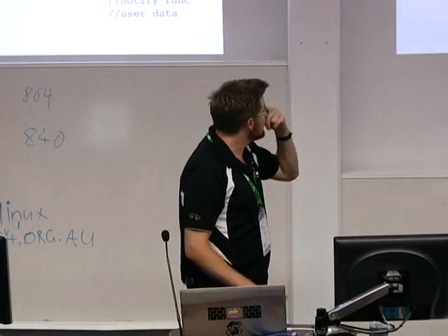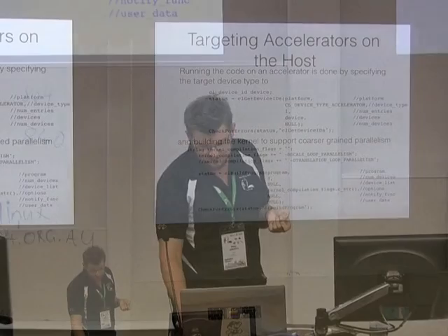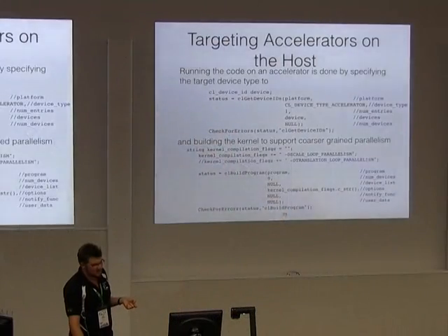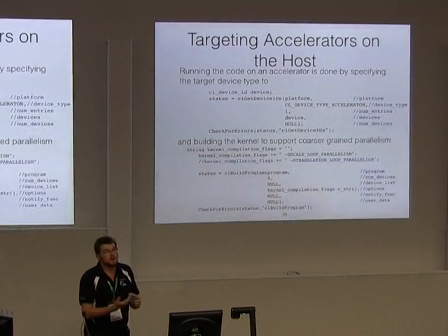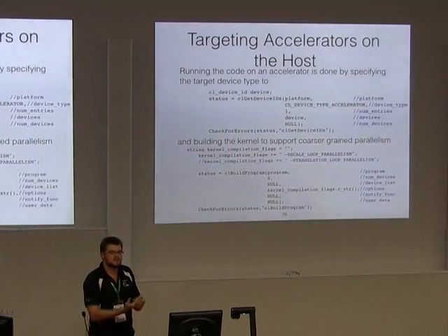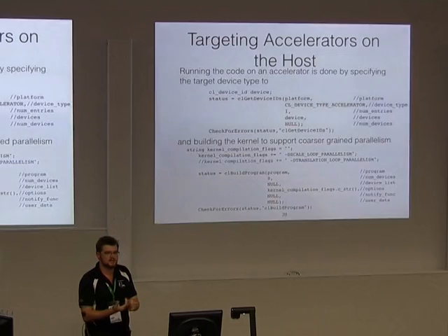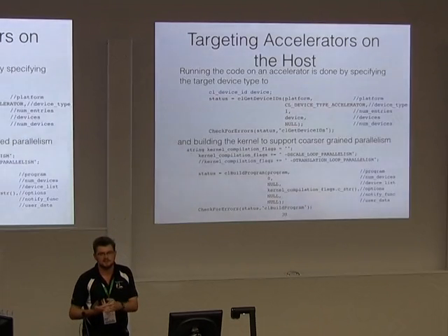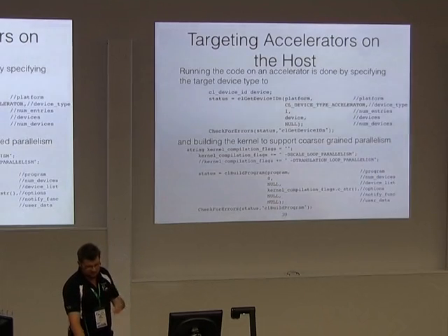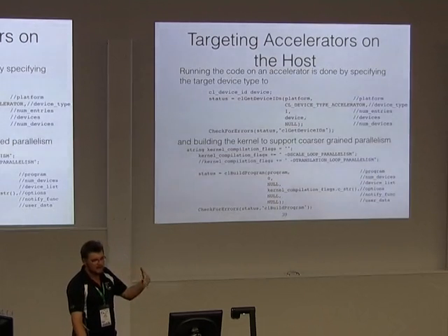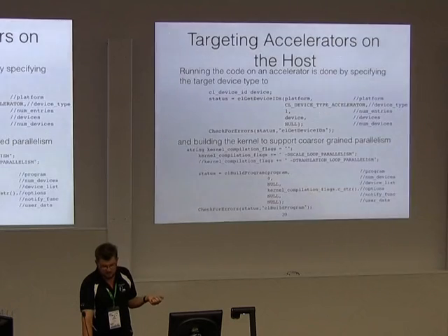To tune it in OpenCL, you set the device type to CL_DEVICE_TYPE_ACCELERATOR now, and that's pretty much all you have to do. The Keystone 2 has 8 DSPs, and each DSP is treated as a thread, so we only set that to 8. But we only really need the outer loop parallelism.